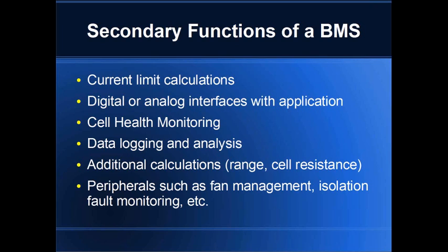In a vehicle, they're often combined with isolation fault detection. So if you have a battery pack that is isolated from the chassis of the vehicle or a stationary application, it's very helpful to know if you have a breakdown in isolation between the battery pack that's supposed to be isolated and the chassis, and that can help prevent more catastrophic external shorts, because it can detect if one short develops before a second one does, before it turns into something more serious.